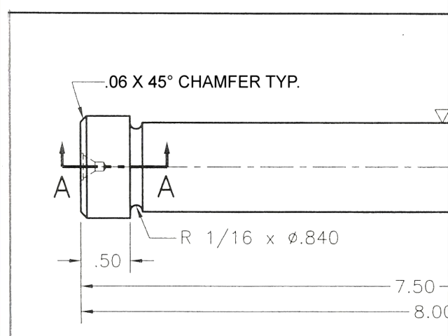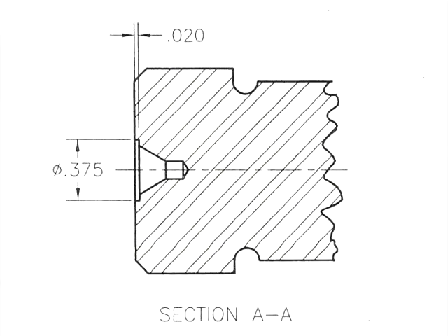In this example, the direction of the arrowheads on the section lines indicate to us that the viewer is positioned on this side of the part and is looking at the section in this direction. And here is our section view, section AA. Well, it's AA because our section line was identified as AA, not because it has a drinking problem.